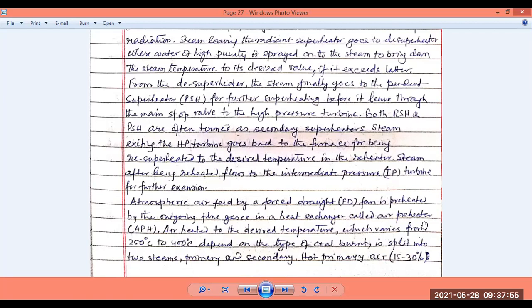The incoming air, forced by the fan, creates the forced draft, and it is heated in the preheater, the APH, the air preheater. So far, before this section, we were heating the steam. Now we are heating the incoming air, first using the air preheater, APH.